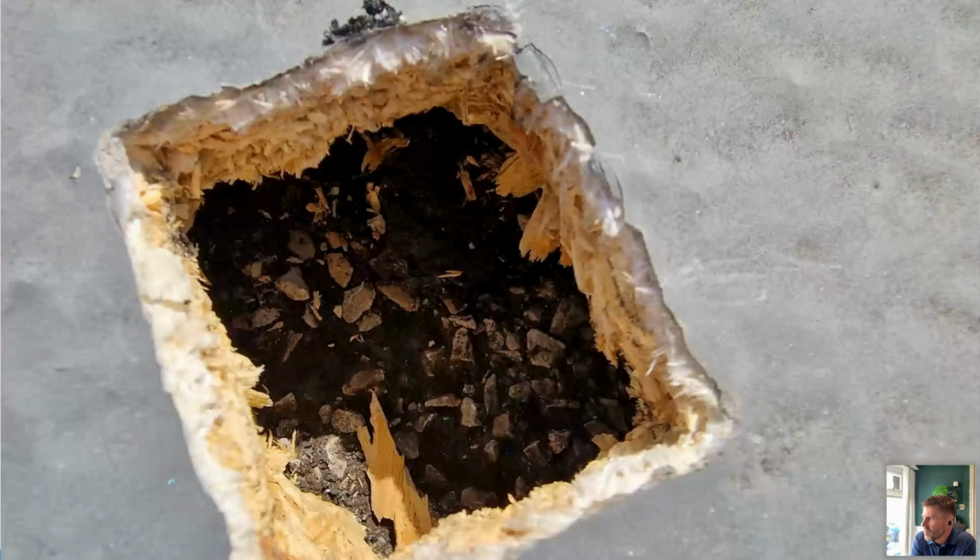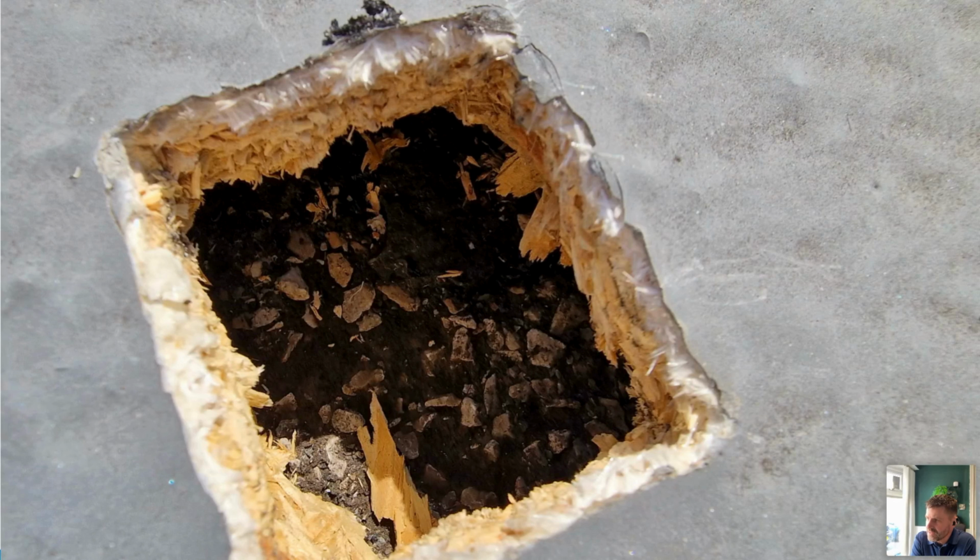This is what we were talking about, an example of a rigid GRP system. You can see the top surface there. They've overlaid that with an OSB board, which we've cored through, and you can see there that there's chippings. So that's obviously a felt roof or an asphalt roof that's got chippings on the top.